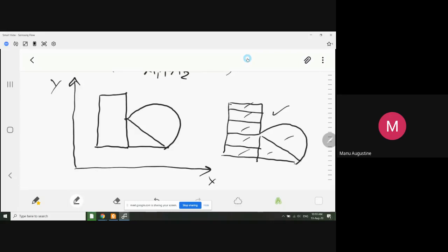Otherwise, if somebody wanted to argue that can I have more smaller areas and can I get more number of areas? Yes, there is no limit to how much partitioning you can do to your given composite area. But increasing the number of areas is only going to increase your task. So the first thing that you have to remember is divide the given composite area into as minimum number of parts as possible, and each part should be an identifiable, recognizable standard shape of geometry.